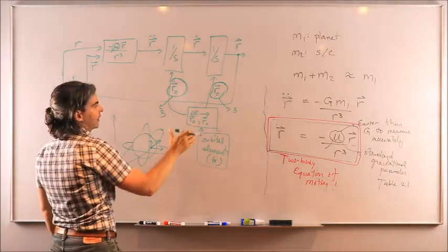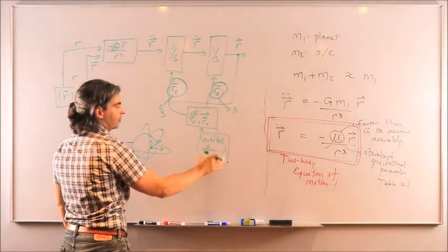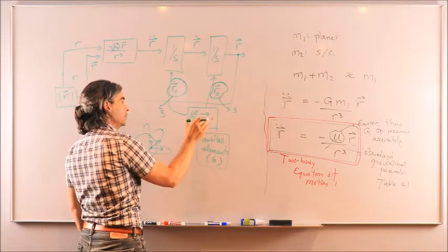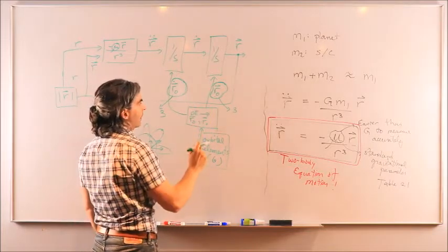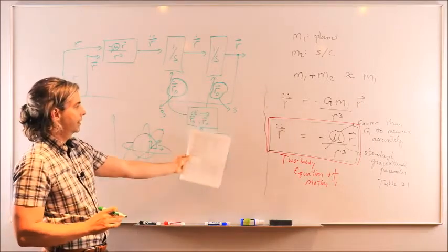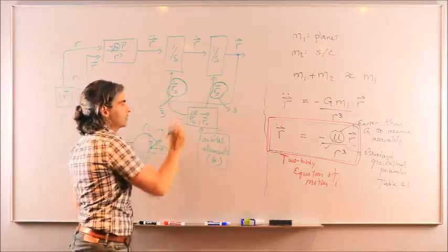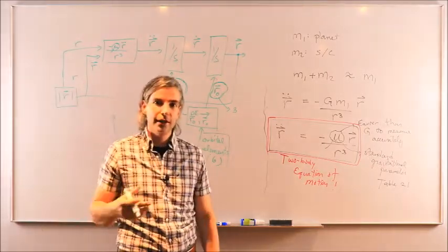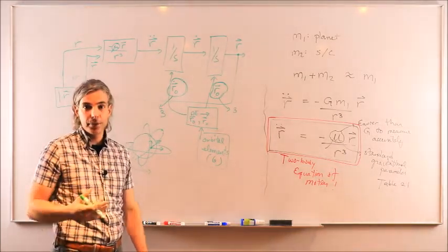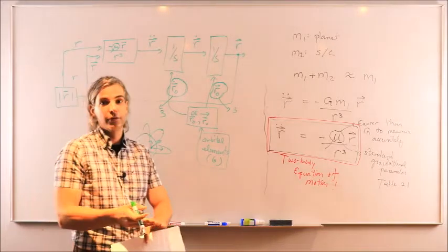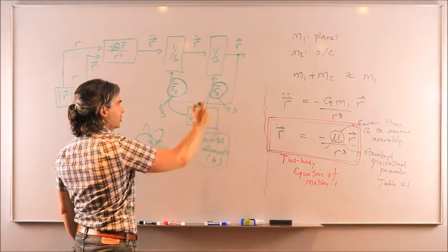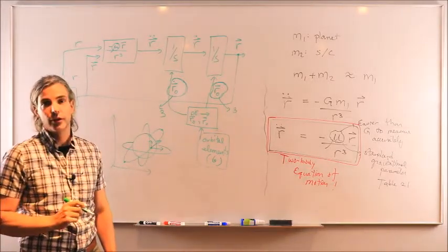So regardless of if you go through the process of selecting 6 orbital elements, converting them into position velocity at t equals 0, or just starting right away from position velocity at t equals 0 without this extra process here, you will always have to select 6 parameters to initialize any type of orbits. And the reason for that is because an orbit evolves in 3D space, where you have position and velocity, both of those in 3D. Okay? So X, Y, Z components for position, X, Y, Z components for the velocity.